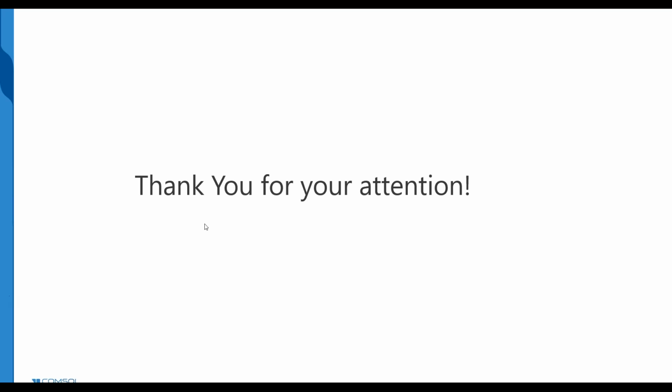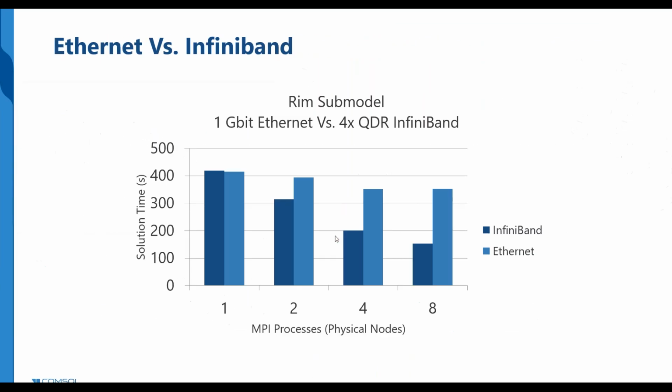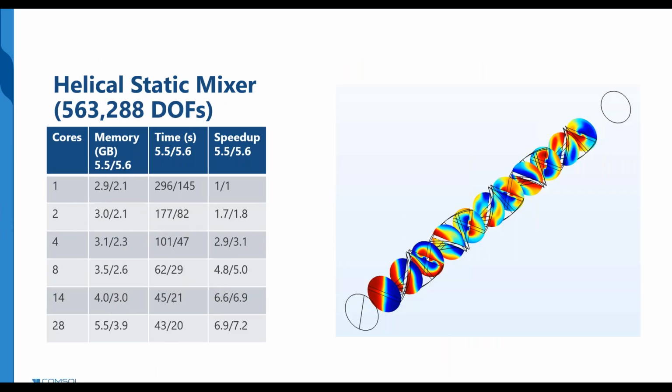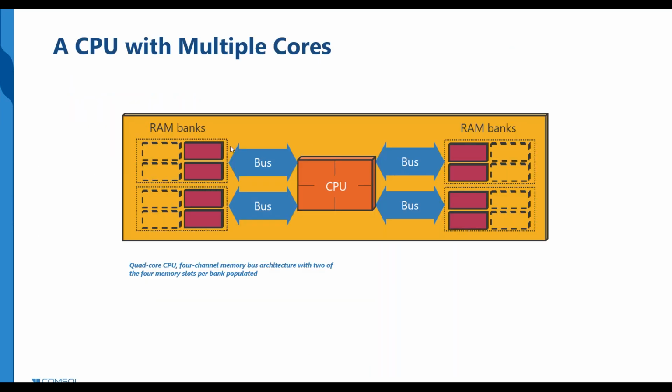More memory can lead to lower performance. Yes, that is actually something that is true. And the reason for that is that when the CPU or the memory banks are populated like this, then the bus can run at highest speed. But there are effects on some motherboards where, when the banks are fully populated, the bus is degraded to a lower speed. And I think that has to do with heat